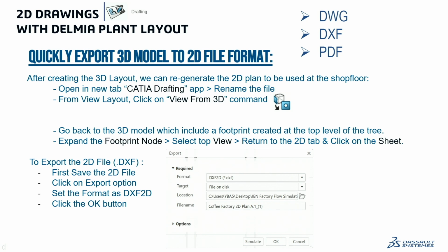And this one too, I can export this out. If you look at the screen real quick, it lets you know, just for your reference, you can then save that out as a 2D file if you want to. You can also export it as an option. So you can do a save as, or you can do an export. It depends on what you're trying to do. Like I said, it doesn't allow you to save a version of a DXF or DWG, but I know I can open it up in 2008 AutoCAD. That's the oldest version I had of AutoCAD. I had the DraftSight too, and it opened up in 2002 as well, so I'm assuming it would open that as well. So it kicks out a pretty generic version of it.